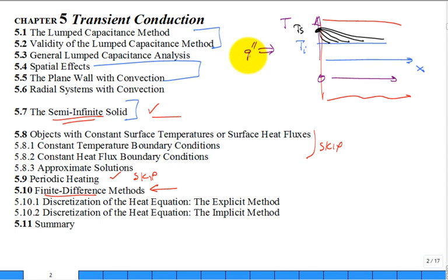Well, what's the application of that? Maybe you have a laser and it's impinging some power deposited at that surface. Okay, that's a possible application. Another one is, don't just move the temperature, don't apply a heat flux, just expose it to a convecting fluid with a different temperature, T infinity, and a convection coefficient. We're going to find that one gives us the longest, most challenging analytic solution, the last case.